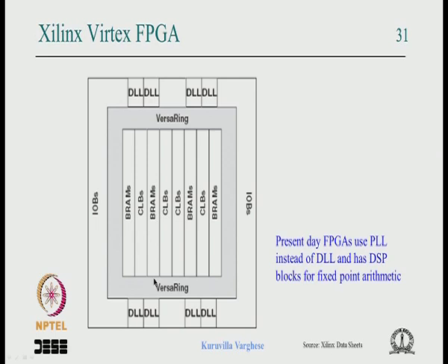In the recent FPGAs you will even find the DSP blocks, which basically allow fixed point arithmetic. You can have a fixed point addition or multiplication and things like that. So those blocks will be built into the FPGA. Then some recent FPGAs might have the ARM processor core built in. Some might have memory controllers built in and so on. So that is, in a nutshell, the top view of the Virtex FPGA.